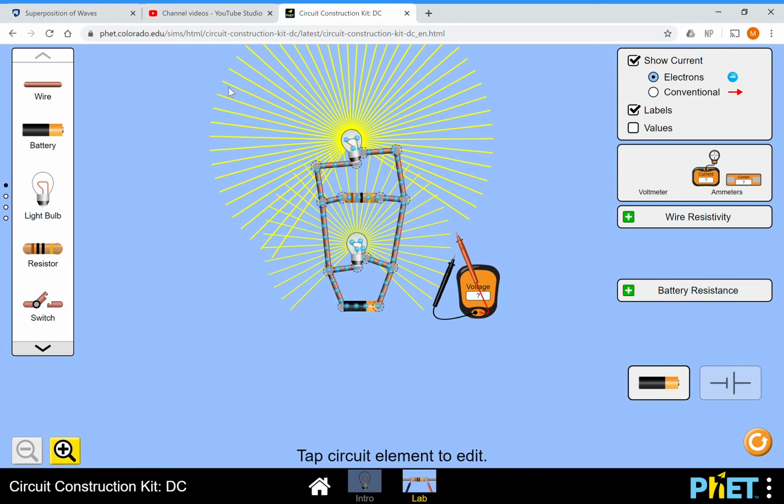Here we see the three things all connected together in the circuit, and they're connected in a very different way this time. This is called a parallel circuit, so there are parallel paths. What's happening is each branch of the parallel circuit has a different amount of current flowing in it. I'm going to try this. We call this a clamp meter. It's able to measure the current in a wire without being thrown into the circuit the way you would normally connect an ammeter.